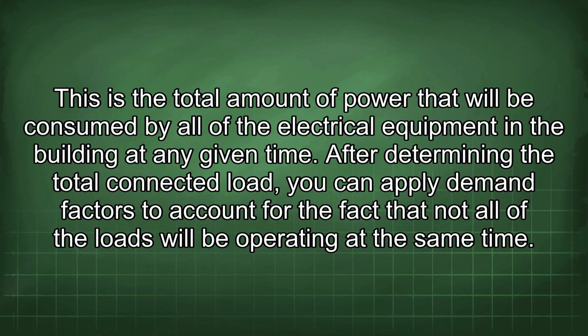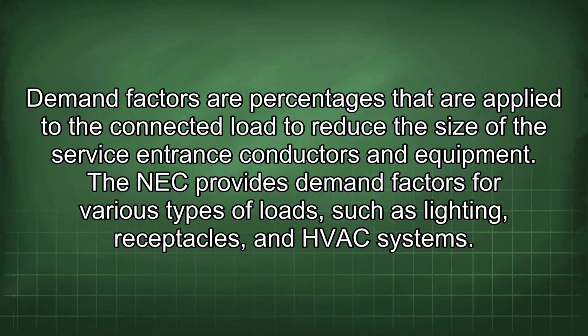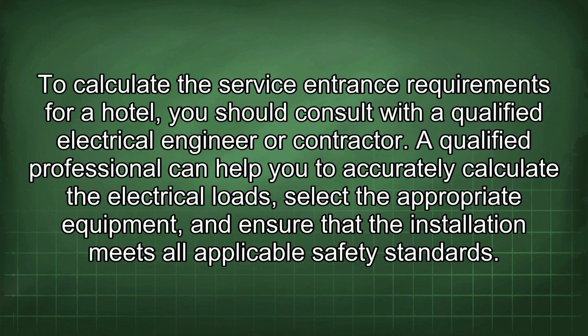After determining the total connected load, you can apply demand factors to account for the fact that not all of the loads will be operating at the same time. Demand factors are percentages that are applied to the connected load to reduce the size of the service entrance conductors and equipment. The NEC provides demand factors for various types of loads, such as lighting, receptacles, and HVAC systems. To calculate the service entrance requirements for a hotel, you should consult with a qualified electrical engineer or contractor. A qualified professional can help you to accurately calculate the electrical loads, select the appropriate equipment, and ensure that the installation meets all applicable safety standards.